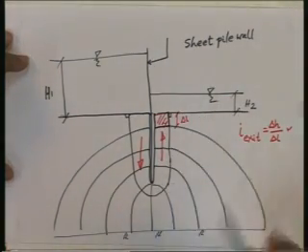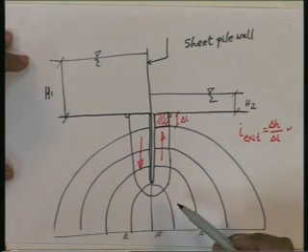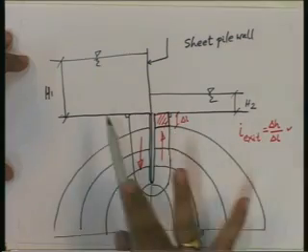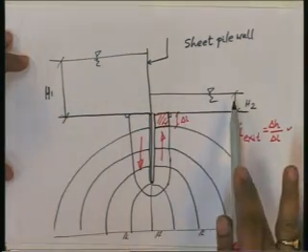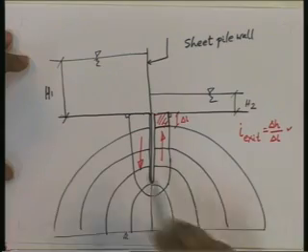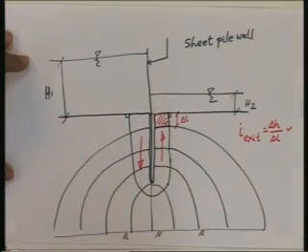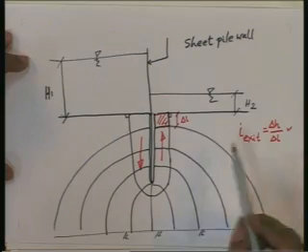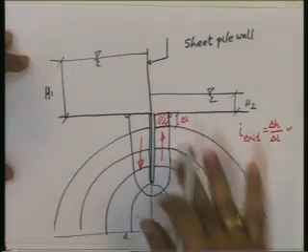That means perpendicular to this figure, per meter width of the figure, if you consider, there will be a row of sheet pile walls which ensures the leak proofness and retains the water with a head H1 on the upstream side, H2 on the downstream side. So, then the flow takes place with a head loss H1 minus H2 over a length here. So, the cross section, if it is given and if it is homogeneous, then if this is a soil, this is how the procedure has to be done.